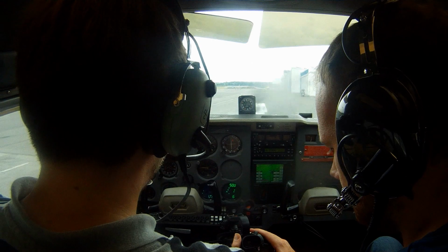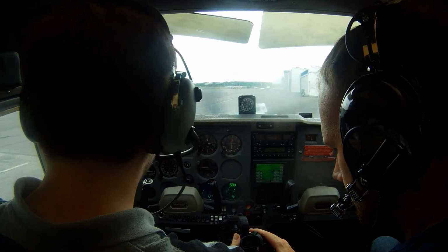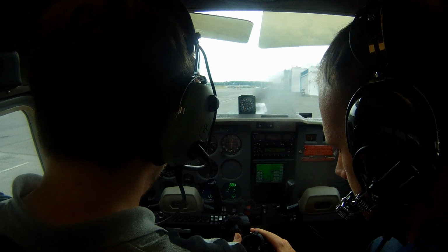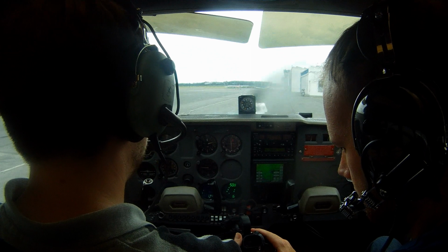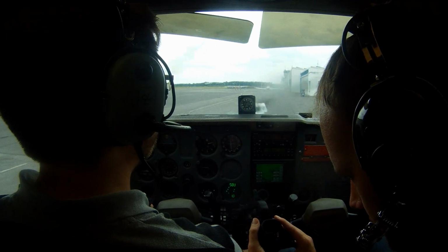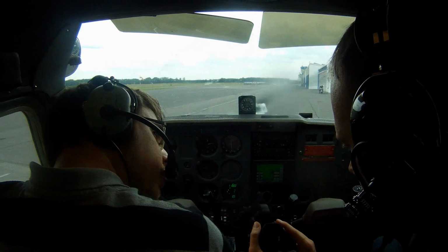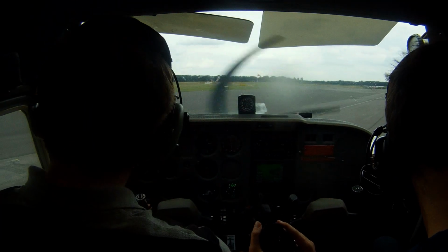Alright, the engine is warm, we're ready to taxi, and we're just going to taxi out of our parking position here, and just after we started rolling we're going to check our brakes, and thereafter in the next turns we will check our gyro instruments. So let me just apply some power to get out of here, and now we're moving. Check the brakes, both brakes checked, and now we're just turning to the left to get to the main taxiway.